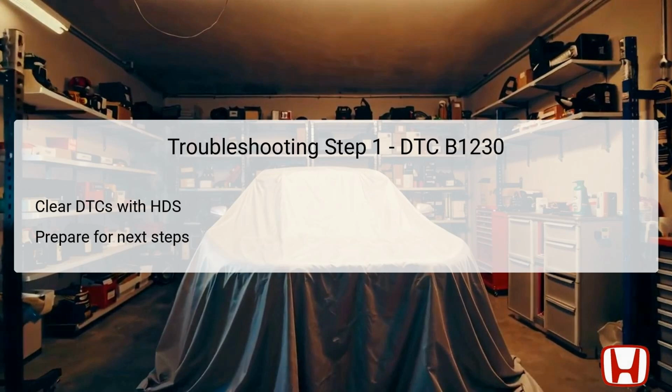It sets up the climate control unit for a fresh diagnostic check, ensuring accurate results for subsequent tests. Clear communication with the diagnostic tool is essential to move through the troubleshooting steps effectively. Following the initial step, the next action is turning the ignition switch to the LOCK (0) position and then back to ON (II). This step is crucial for properly initializing the vehicle systems after clearing DTCs.